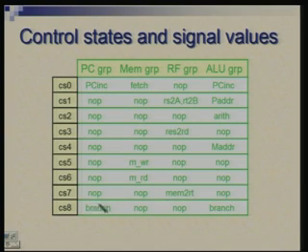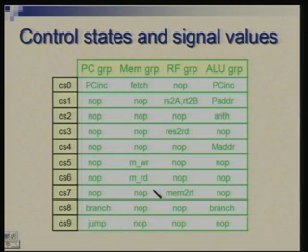So, again the branch micro operation shows up in the PC group as well as in the ALU group, because it requires a comparison here and it needs to change the state of PC. So, both these get influenced, and CS9 completes the jump instruction. So, it is influencing this PC group. What I can do, but I will not do that here, is replace each of these micro operation symbols by a bit vector. Okay. That bit vector defines the relevant control signals.